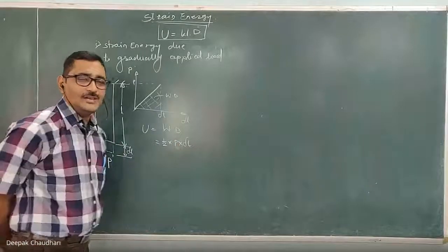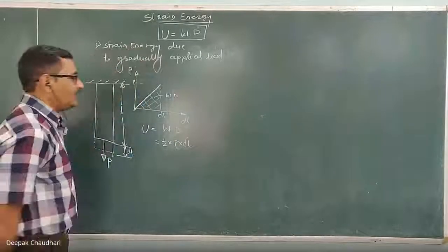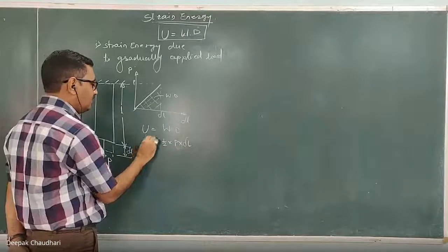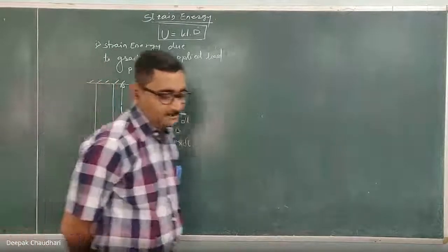Not only P into delta L, but it is half into P into delta L. Here it is the area under this graph. Here this is the work done, which is equal to the strain energy stored in the material.